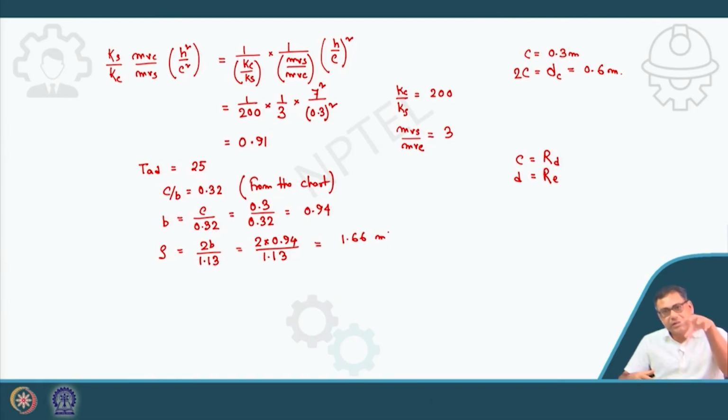Though the permeability has a negative effect, stiffness has a positive effect. If you consider them individually, stiffness will reduce your RU value and permeability will increase your RU value. But in their combined effect, as the permeability has the higher or more significant effect compared to the stiffness, overall the net RU value will increase.